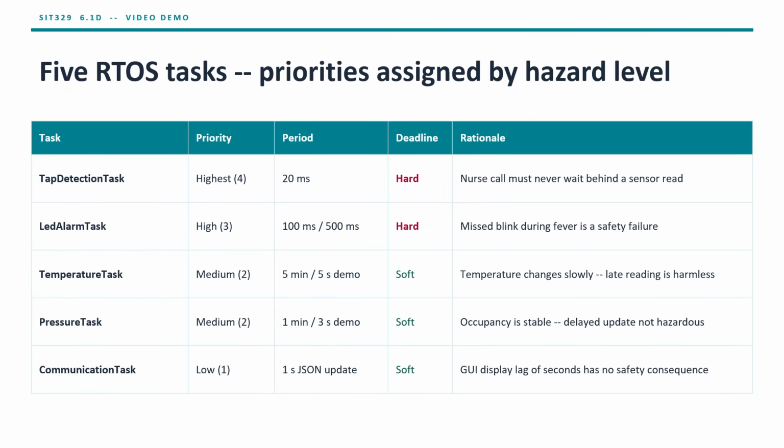Its deadline is classified as hard, meaning a missed response has immediate safety consequences that cannot be corrected after the fact. LED alarm task is the second highest priority, because if the LED fails to blink during a fever state, the nurse receives no visual warning at the bedside. That is also a hard deadline.